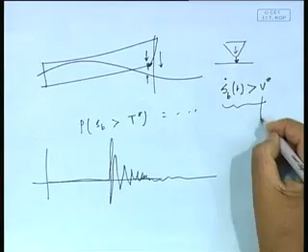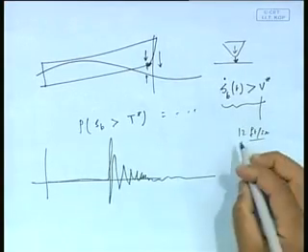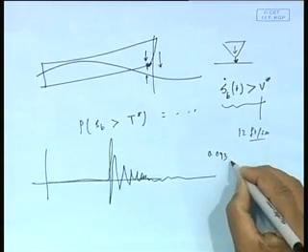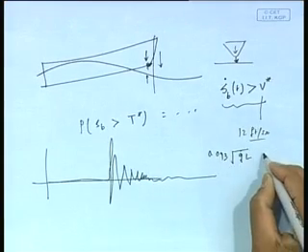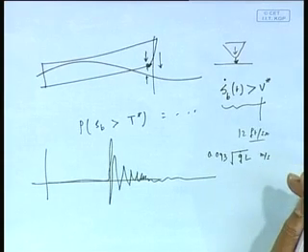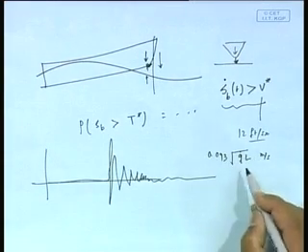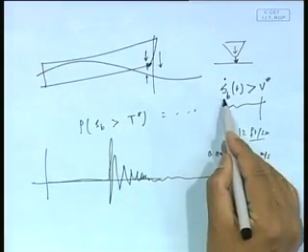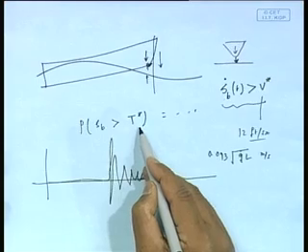For example, at one time this was known to be 12 feet per second, but there is an empirical formula, which can be written as 0.093 root of GL meter per second. So some norms are there. So we will say that slamming occurs if the probability of this is more than this, as well as the probability of this is more than this.